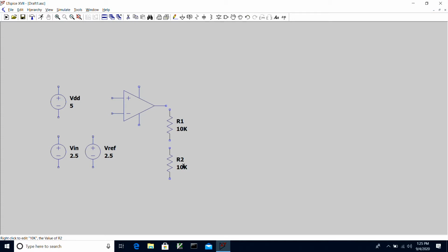So the MKS prefixes are not case sensitive. That's why there's confusion between meg and mega and milli, and so they disambiguate that by making the prefix for 10 to the 6th MEG, meg. That's a very common trap for people who are new to Spice to fall into.